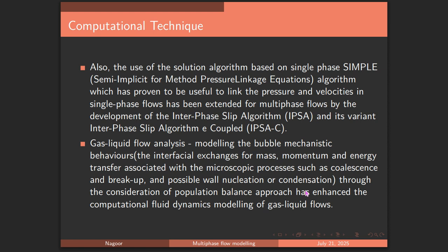And moreover, there are other techniques, like the population balance approach, also utilized in gas-liquid flows. I'm giving some examples, and there are also other techniques utilized in gas-solid flows, how the solid equations are formulated from Newton's laws of mechanics, and how, when the solid particle passes through a computational cell or finite volume, it will interact with the gaseous phase, whether it will be one-way coupling or two-way coupling. So those modeling techniques we have also somehow borrowed from single phase techniques.